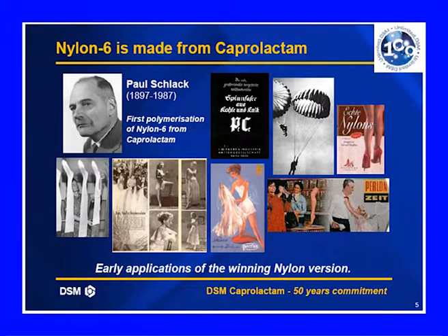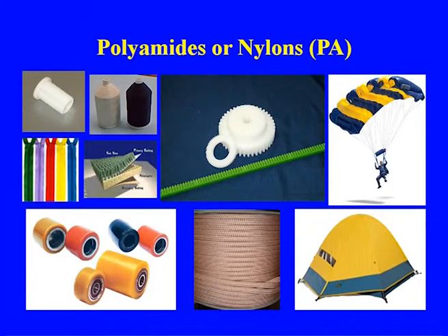of nylon 6. Now it is not only in synthetic fiber, meaning the woven industry; a huge amount of nylon 6 is going to the non-woven industry. Even in electrical appliances we are using nylon 66 and nylon 6, and there are threads, parachutes, and other applications. Especially, as I told you, electrical applications like switches and MCBs, where earlier we used Bakelite switches, but now we are using nylon 6 or polycarbonate.